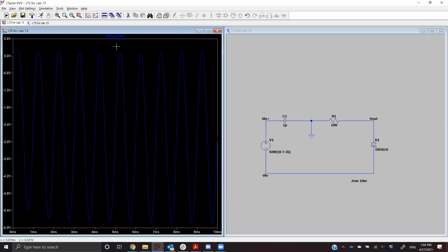Now, in several cases, what we're really interested in is the RMS after the signal has reached its steady state point. By that I mean, if you look at the initial part of this graph, it looks different from the rest of the graph, right? Towards the end, it is a more periodic signal, whereas towards the beginning, it's gradually dropping. So this is what we call an initial transient. And what we want is actually to calculate the RMS of the final part, just this part.